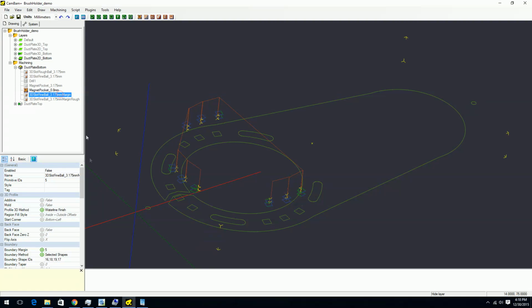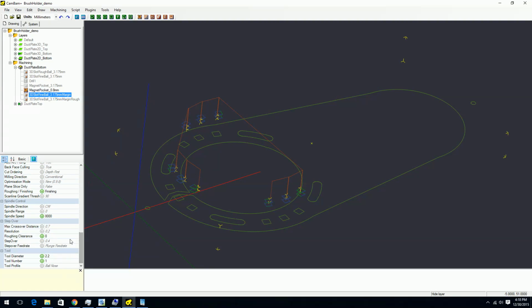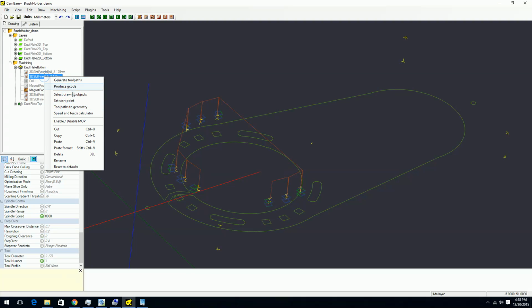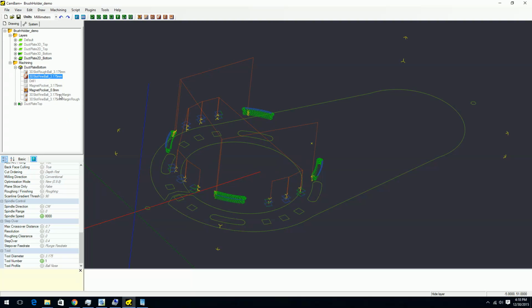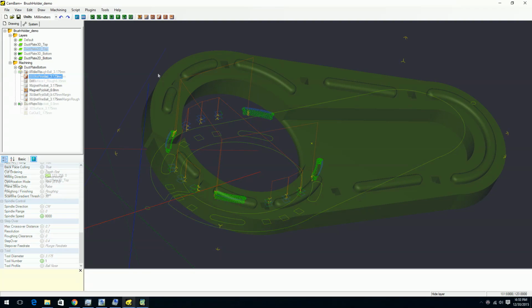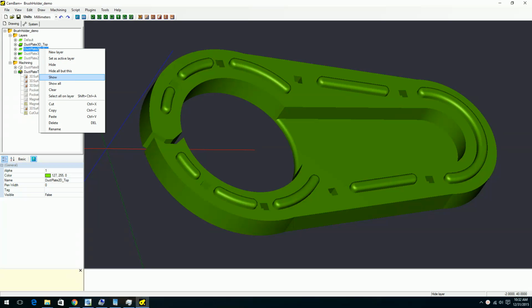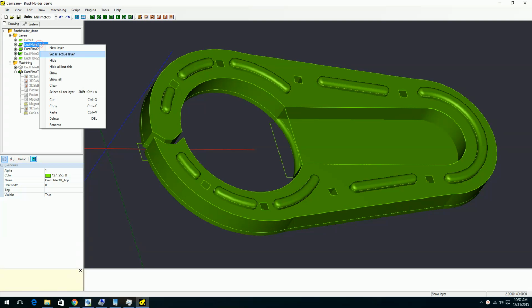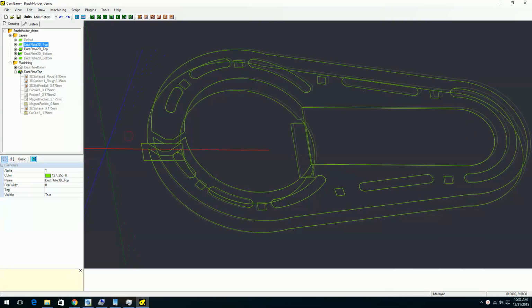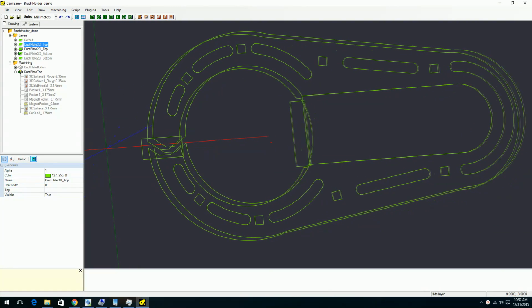Now from experience I know that if I machine the part exactly to specifications, I will not be able to easily fit the parts together later. So what I'll do is make another machine operation in which I do exactly the same operation as the roughing operation here, using the same bit, but specifying a smaller bit diameter. That will basically make the hole a bit bigger, and that will allow me to later align the two parts together very smoothly.